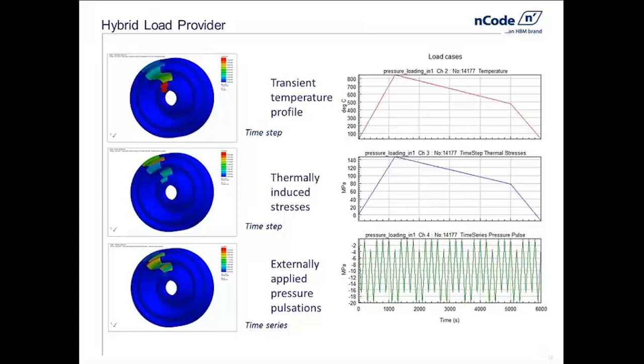We typically find in temperature-based fatigue that we have some loads of fairly long duration, such as thermal transients. The temperatures themselves, and if the temperature change is generating stresses, the stress history as well, will be a fairly long duration condition. If we have mechanical cycles with that, the mechanical cycles tend to be at a much higher frequency than the thermal.